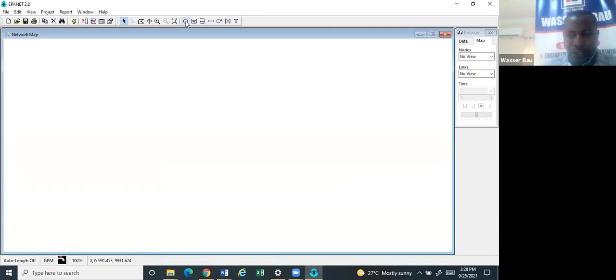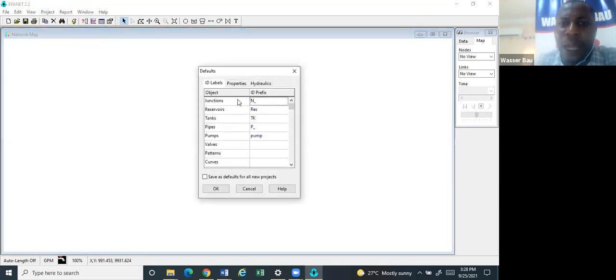Yesterday, we were talking about node 13, node 6. So node 6 is a node, node 13 is a node. So when you want to put a node, this is where you add it, and so on and so forth. So the first thing I do is go to my project, I go to my default. Now I will say junction will be represented by N. Junction is like a manhole. It's a place where the elevation values are known, and where water demand is known. In real life, that is where they will install a water meter.